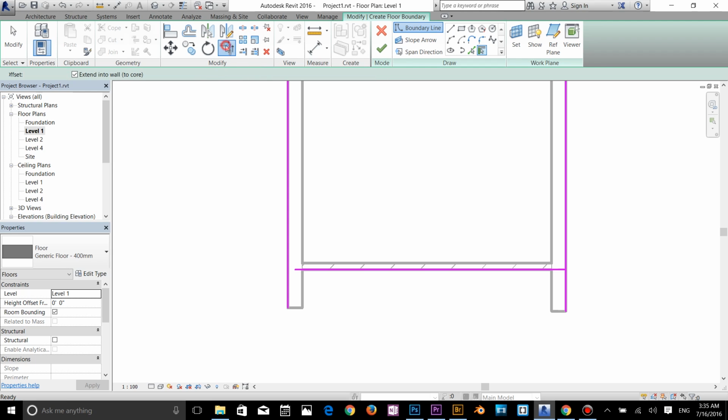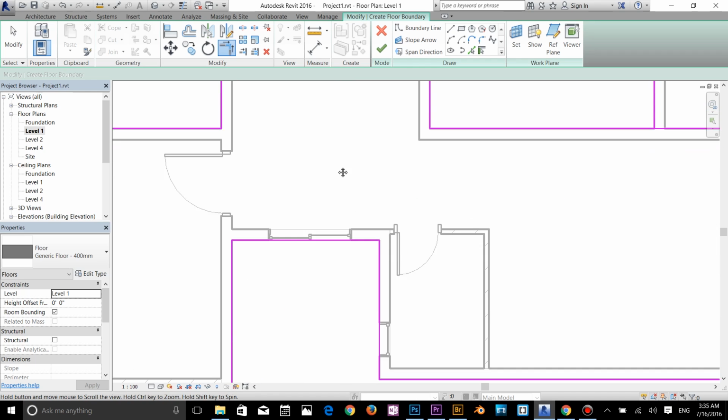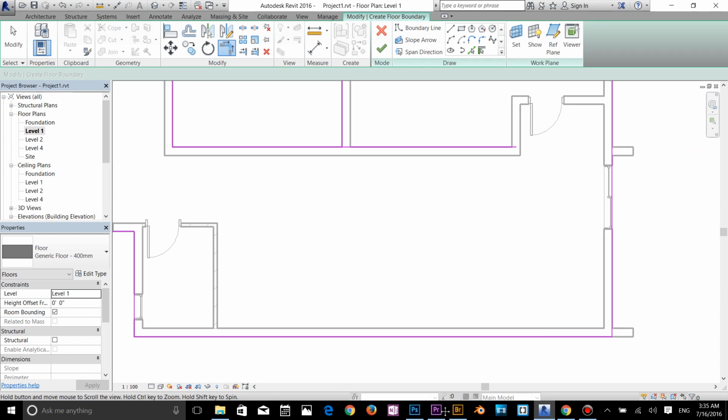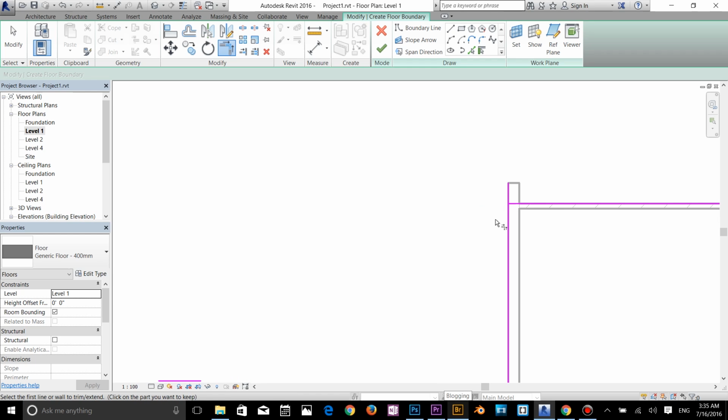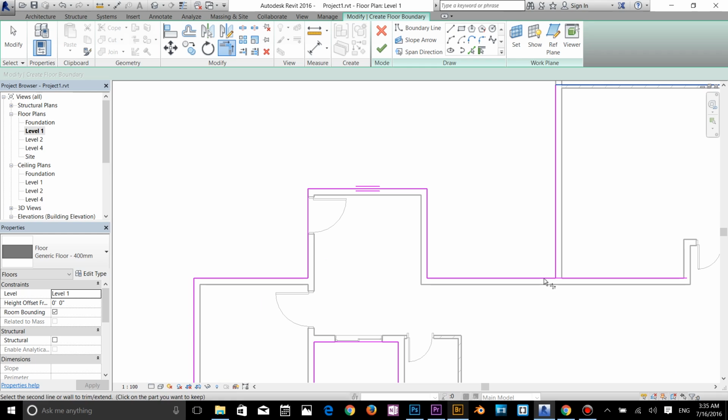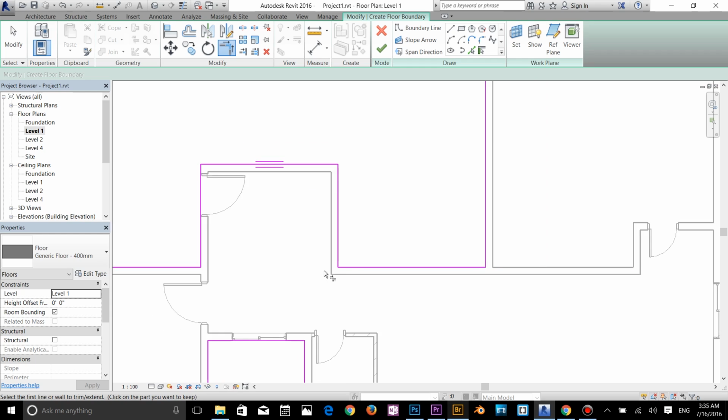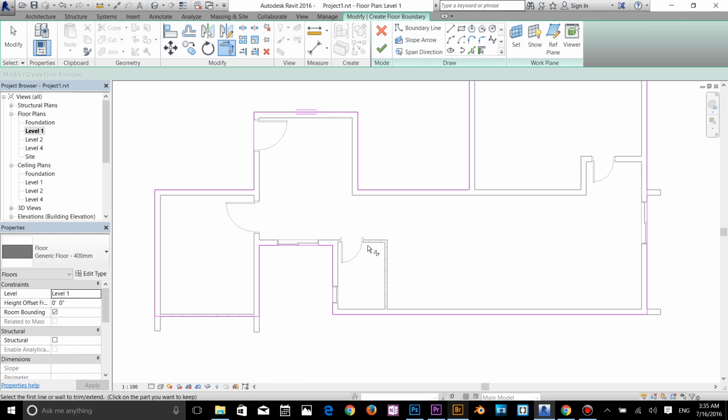So I'm going to select trim and extend command. This is kind of like the fillet command in AutoCAD. So select this line, it's going to fix that for us. Alright, so pretty much that's fine here. Need to fix this one and fix this one as well, and then you gotta fix this one. Yep, and yep, that's fine now.